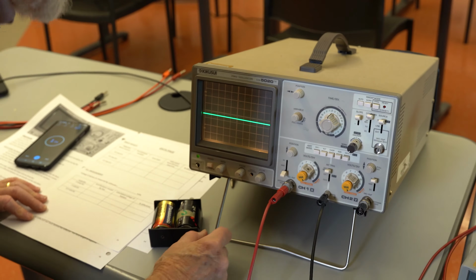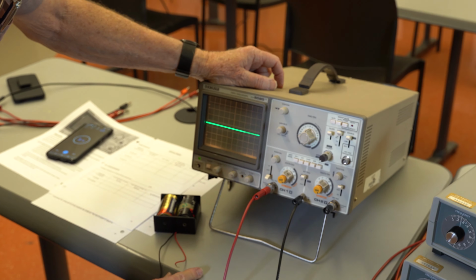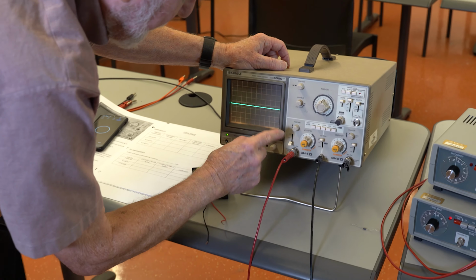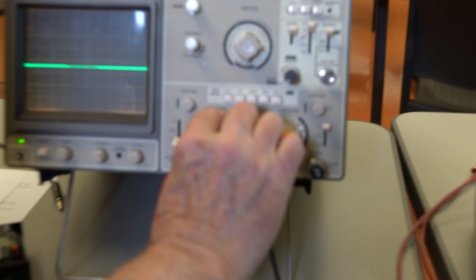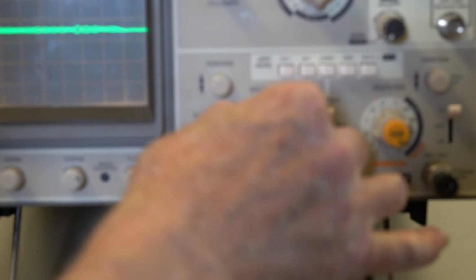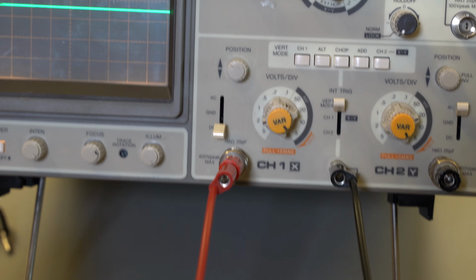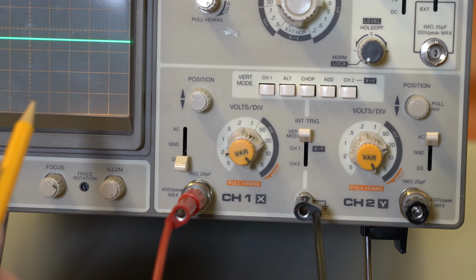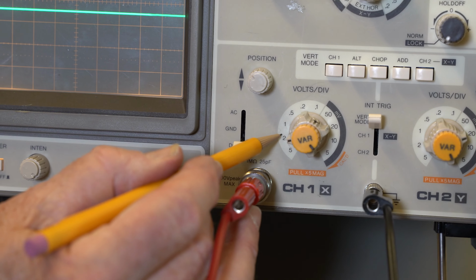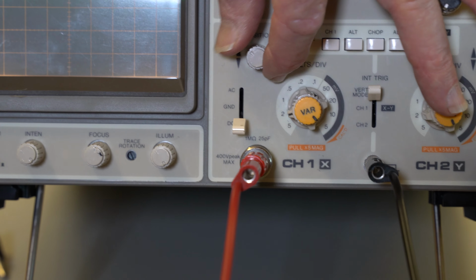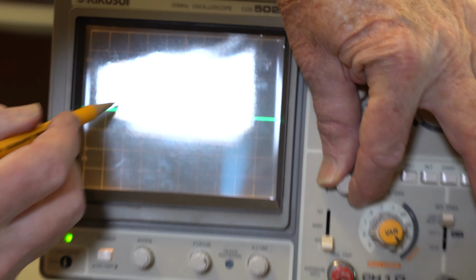Okay, we can also use this device to measure voltages. So this is our voltage input, and this is the sensitivity of the voltage. As we turn this knob, it becomes more and more sensitive to the voltage input. The instructions are to start with a 2 volt per division setting. So here we have 2 volts per division. Now I'm going to use this position knob, you see the up and down arrows here, to set this right on the 0 mark, the 0 line.